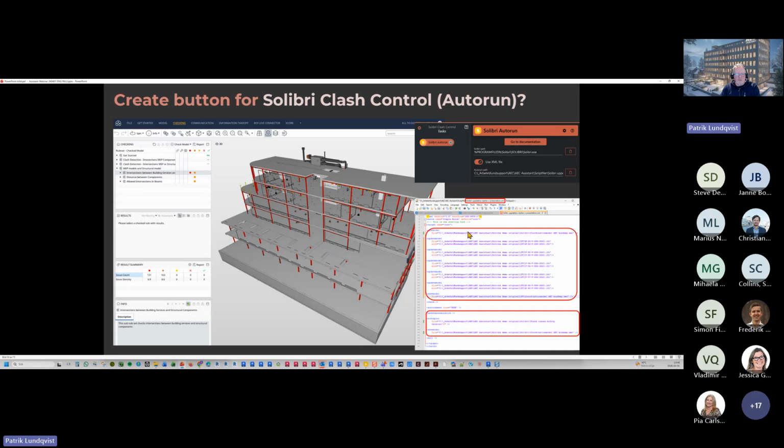In this case, we can see this is something you can just get from the Solibri web page, or you can have it created. This one updates clashes and updates the presentations where you can see all the clashes. So it opens the file. In this case, it's the same file, only with just a structural part. And then you can update all the IFC files necessary. You save it as something, SMC, and then you zoom out and then you do some tests.